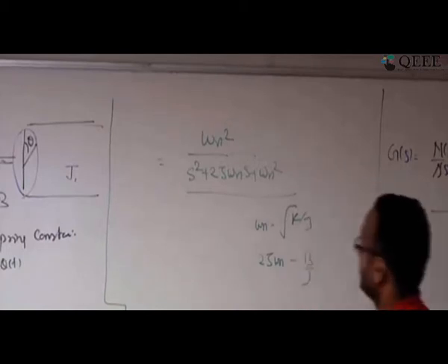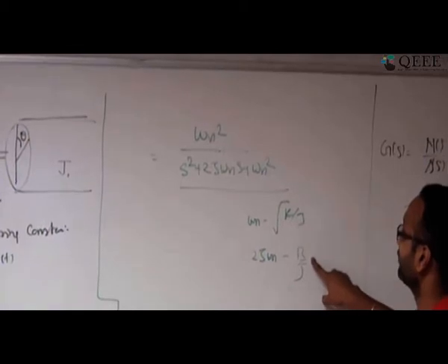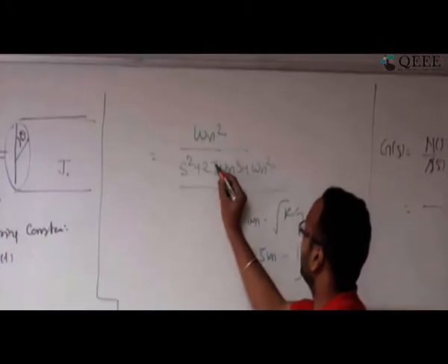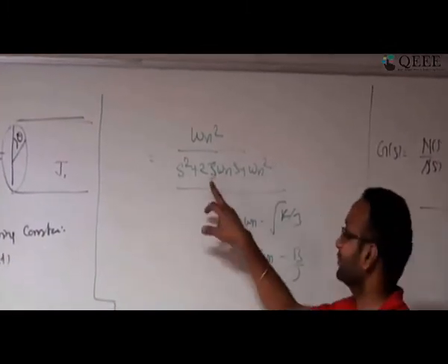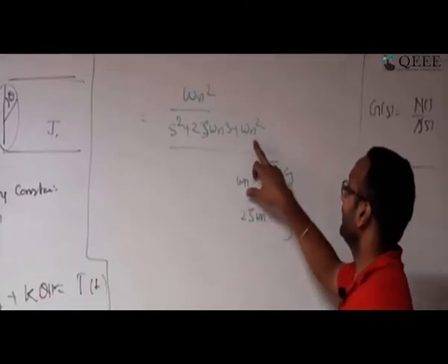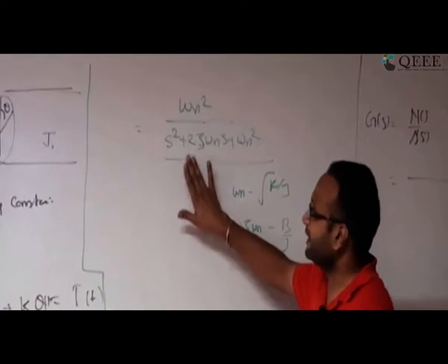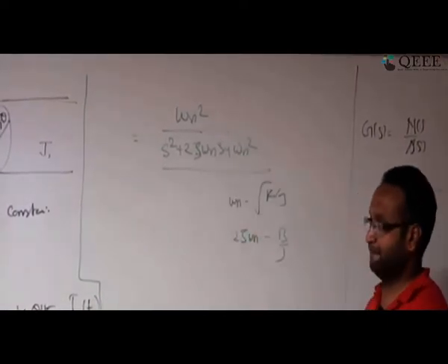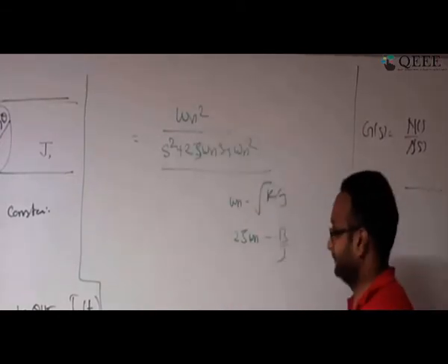So look at it, now instead of this spring constant, moment of inertia, viscous friction coefficient, I will be talking in terms of zeta and omega n. This 2 zeta omega n, sometimes people use rho also, so I am calling this term rho. This is omega n square over s square plus this one. Correct? This is the way I am writing my standard way of expressing a second order system. Okay. So as I mentioned, from here onward I will be using this term only.